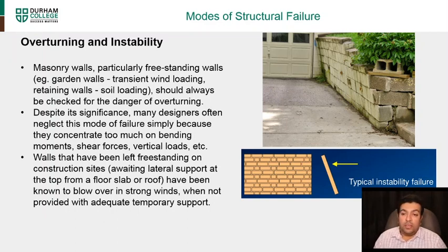Another example of this is walls during construction. If walls are left freestanding on construction sites, awaiting lateral supports from the top and bottom floor, sometimes due to heavy winds, you can see them blow over due to strong winds, right? So that's another failure mode that we have to take into account.